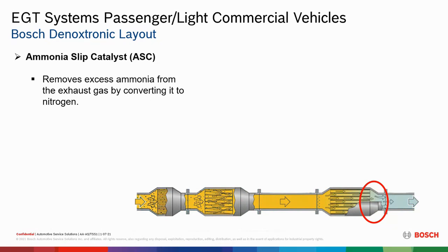And again, on and off the throttle, let's take an example of how we get extra ammonia in the system. Let's say we put our foot in the throttle and NOx goes up high, and the DCU finally says, okay, we've got to start dosing because my NOx levels went high according to the NOx sensor. So we start dosing in there. Now we're equalized under the same load conditions, let's say, and this truck is going up a hill with a boat behind it, cranking up this hill under real heavy load.